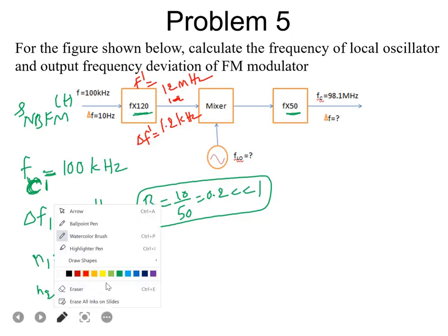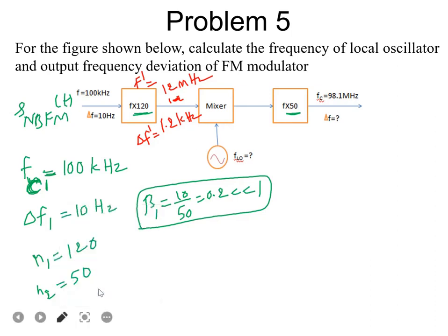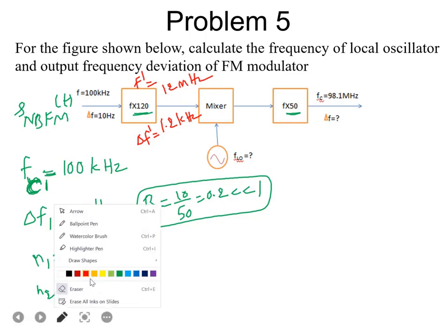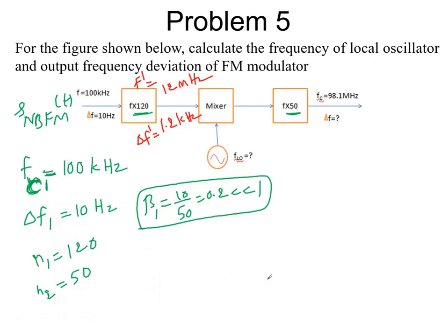The current case, then it is passing through a mixer. Now you have seen what will happen. What is the role of a mixer? It will try to take the difference between these two. For suppose FLO, you assume FLO minus 12 in terms of megahertz only you try to take. Obviously second local oscillator frequency will be there in megahertz. There is no change in frequency deviation, that is del f dash is 1.2 kilohertz obviously.